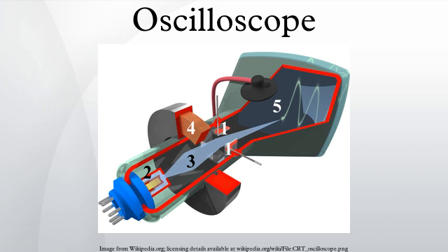Features and uses. Description: the basic oscilloscope, as shown in the illustration, is typically divided into four sections: the display, vertical controls, horizontal controls and trigger controls. The display is usually a CRT or LCD panel which is laid out with both horizontal and vertical reference lines referred to as the graticule. In addition to the screen, most display sections are equipped with three basic controls: a focus knob, an intensity knob and a beam finder button.